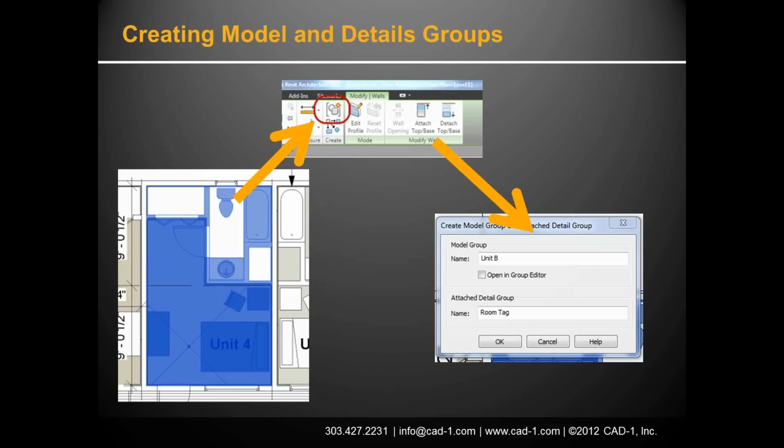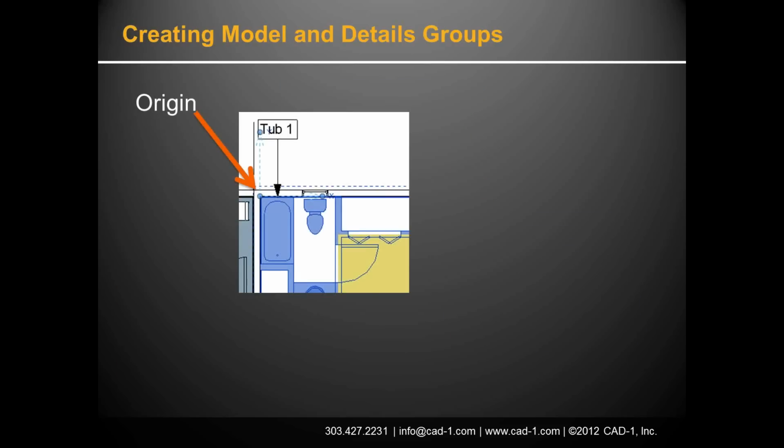All right. Within the groups, and again just talking about a little bit of the workflow here, we've got defining the origin points. You can see here this little XY area, this little dot in here. We define that origin as part of establishing the group. After you've made it, you want to put that origin point in place. That's something some people might forget about. You want a good place to put this origin, especially if we're going to use this in multifamily, or for grouping multi-story buildings, or when we have different unit plans that we're going to repeat. Maybe we're doing labs in a hospital or hospital rooms, different ways of looking at this, okay?